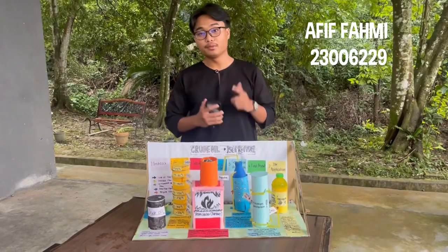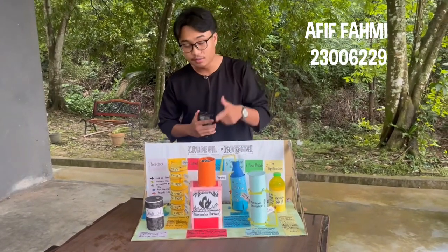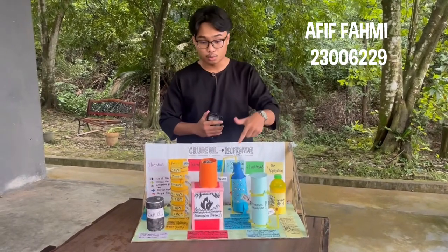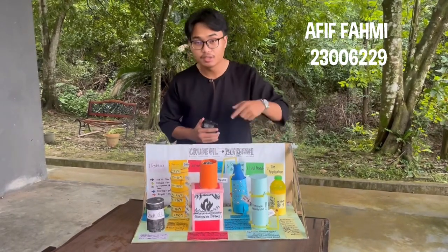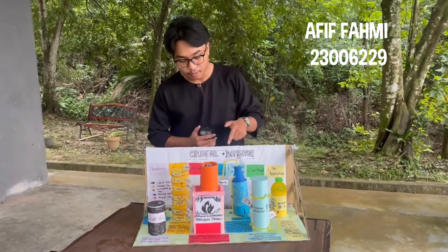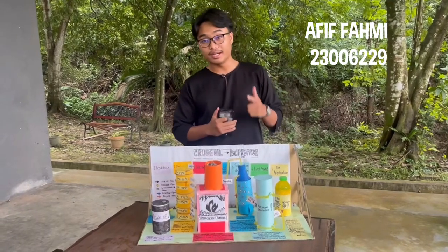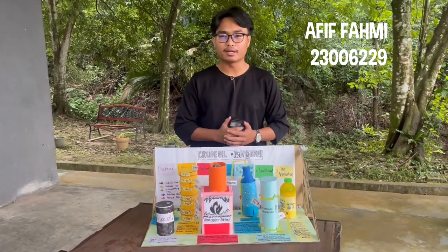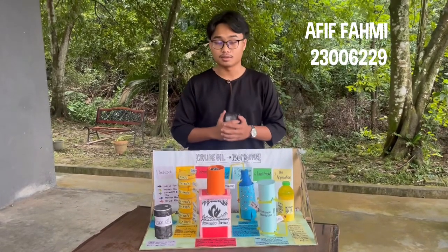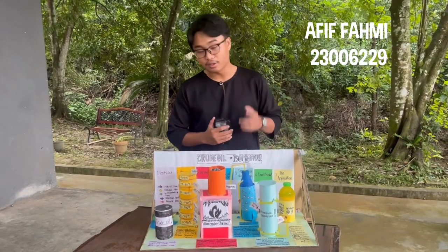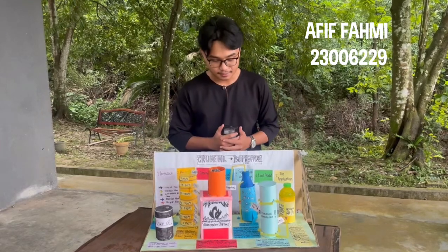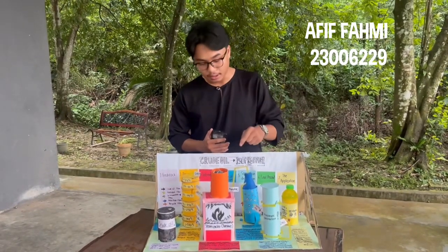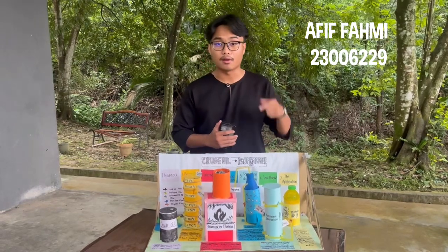Now, taking purified propylene from the steam cracking furnace, we are going to pass the propylene through a pipe to the hydration reactor, where the purified propylene is reacted with water in a direct catalytic hydration process over solid phosphoric acid catalyst. This will turn propylene, also known as propene, into isopropyl alcohol.